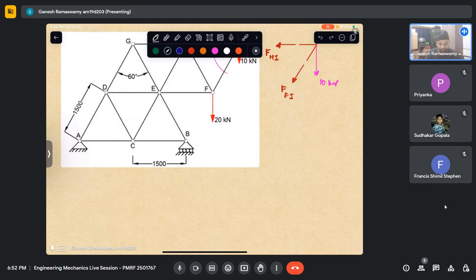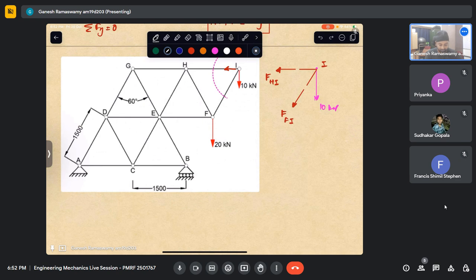If I have all these free expansion allowed, then if I heat the system, let us say, if I heat the truss, then this is free to expand. There will be no forces developed in the members. Whereas if I have an over constrained system, now if I heat it, because of the heat also, the members will experience some force. So that also needs to be added. These are anyway matters of higher level courses, but this is what an over constraint system is. Okay. Are there any other questions?